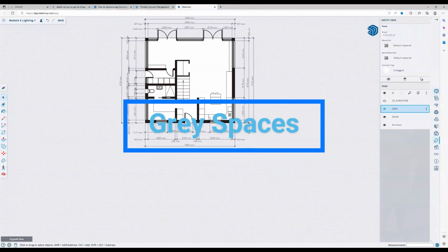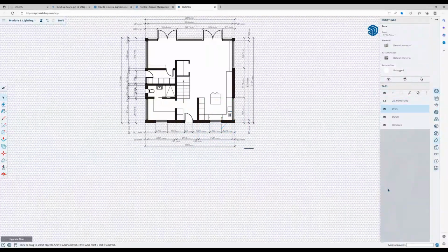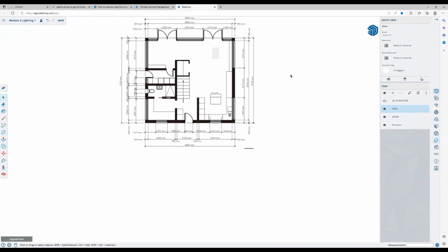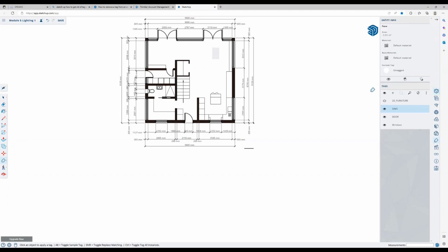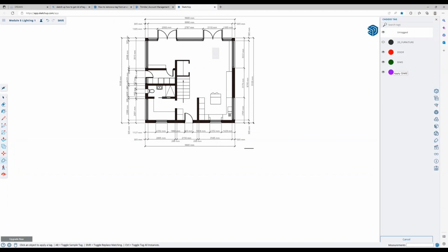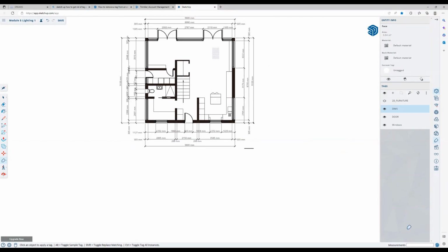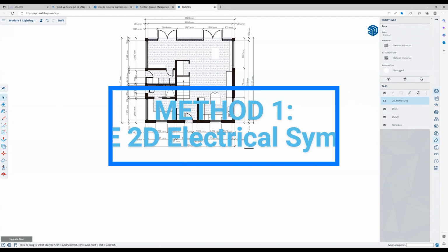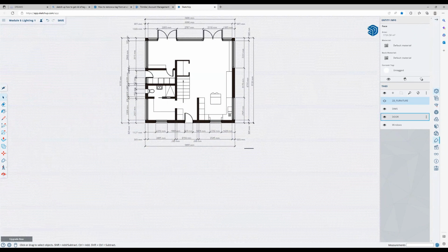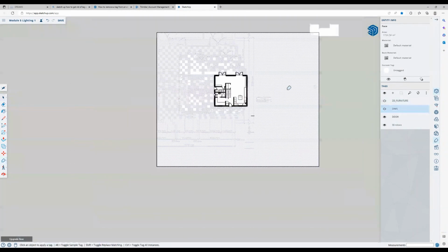Cool, the background stays. So if you're getting any gray spots, I suggest that you check your tags because they could be assigned to something. So I know here, see, this is the coffee table. If I turn my untagged off, but if you assign it to something else, it will remain. Okay, cool. That makes me happy. All right, so we've made for a clear floor plan. And I'm going to turn the dimensions off. Awesome. Cool.